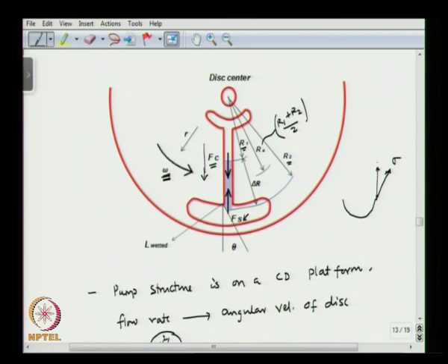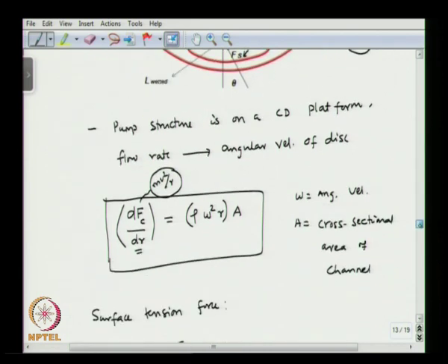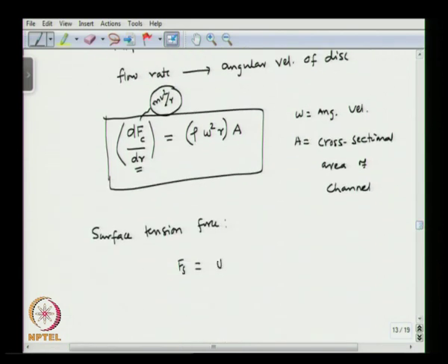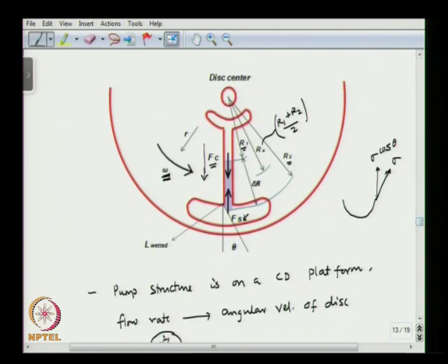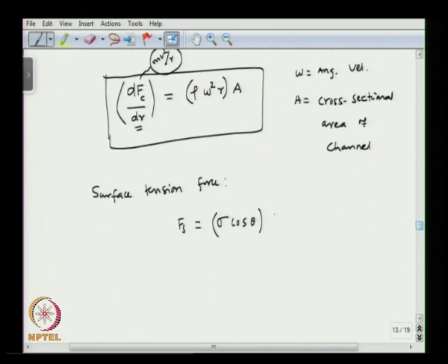So, we are interested in this component. So, this is going to be gamma cos theta, where theta is the contact angle. Okay. So, this we have already seen. So, this would be gamma cos theta, and that gamma cos theta is going to act on this weighted perimeter. Okay. So, the weighted perimeter is going to be pi dh. Okay. So, let us for now call it L weighted. Okay.